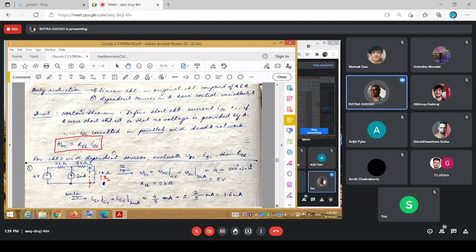Right. So you're as if breaking up the circuit across this point. So this is your A and that's the B part. Thevenin equivalent. So we are interested in the open circuit voltage across these two points. So V of OC, here we are applying superposition. So due to the 4 volts, due to the 2 milliamperes, the two open circuit voltages.